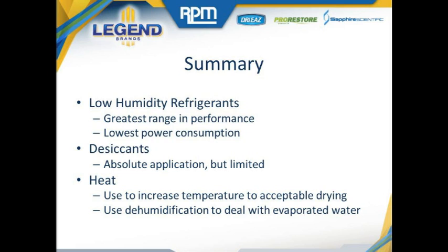Heat, however, as a drying process, continues to be advantageous when we have access to exceptionally dry air on the exterior of the structure. This allows for the use of outdoor air while maintaining a low vapor pressure in the environment and preventing the push of water vapor within the space to uncontrolled areas where secondary damage can occur.